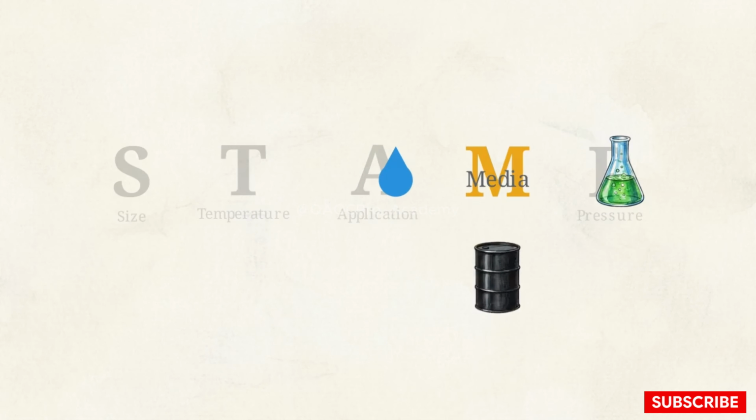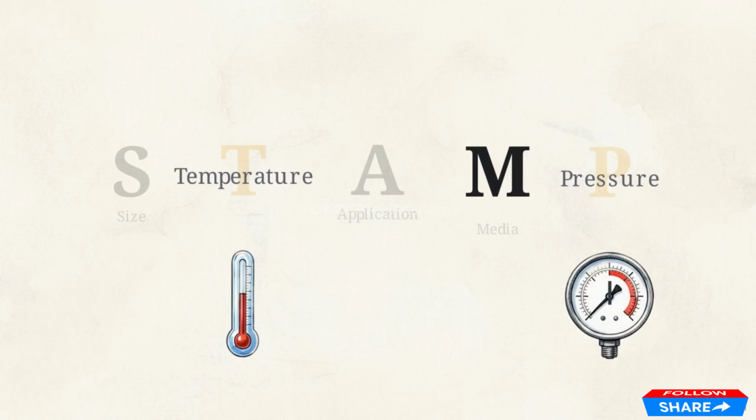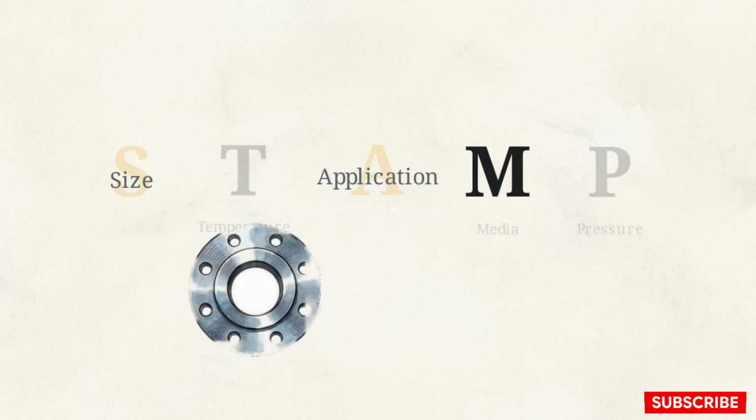Starting with the M, the media dictates the chemical resistance required. You need to know exactly what is flowing through the system, whether that is water, strong acids, or hydrocarbons, to ensure the gasket will not dissolve on contact. Moving to temperature and pressure, these variables test the physical limits of the material. They determine if the gasket will melt, become brittle, or blow out under the system's operational loads.